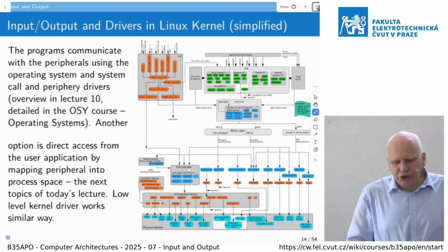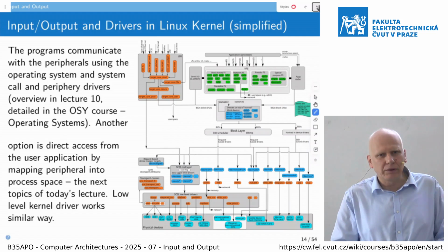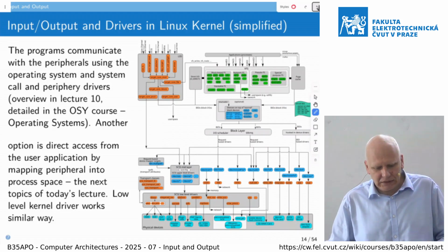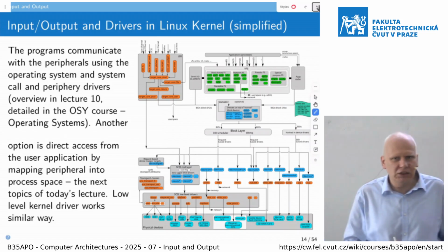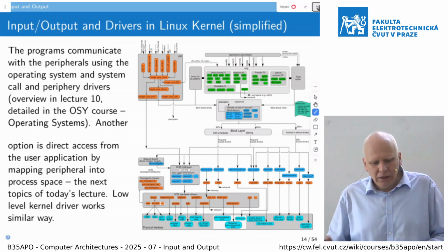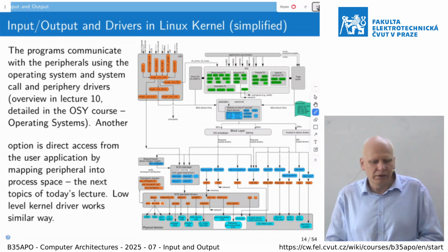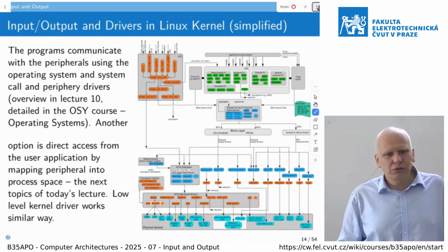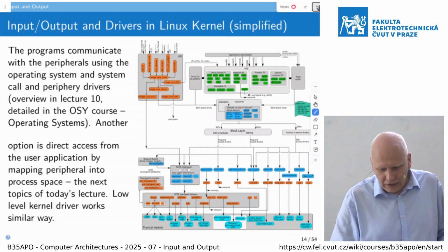there is even an option to access the hardware directly, which is what we will use during our semestral project, because if there is something mapped to the physical address space, then even though you are running in the virtual address space with your application, if you have proper rights, you can remap part of the physical address space directly to your virtual address space and then use an instruction to access a memory range, which in fact will access the actual peripheral.